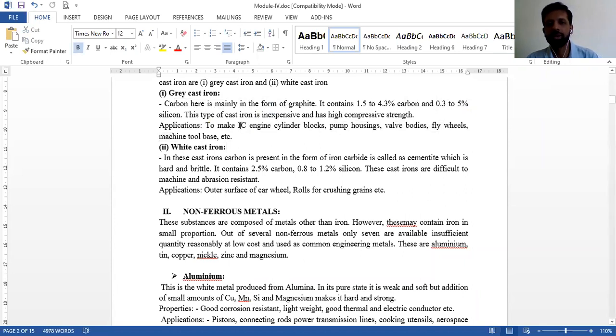Of course, nowadays what we are seeing in two-wheelers and four-wheelers, the engines are not made of iron, but even now in the high-end engines, especially for the railway diesel engines, those engines, the piston, connecting rod, crankshaft, the engine body or cylinder, everything is made of cast iron only, not of aluminium.